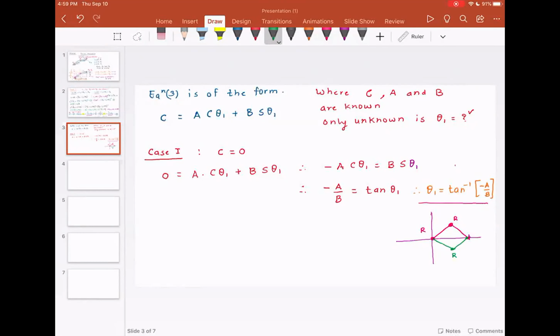But if you were to use the tan inverse function, it will just give you the solution in the first quadrant. So the function to use in robotics is called arctan, which is arc tangent. The MATLAB command for arctan is atan2, and you would have y comma x in parentheses.